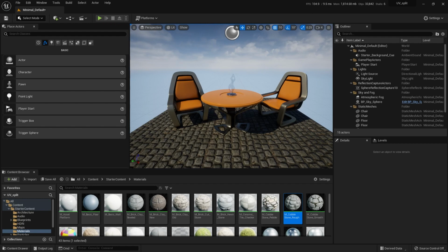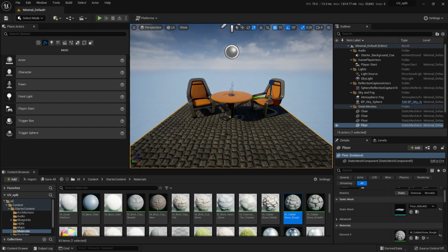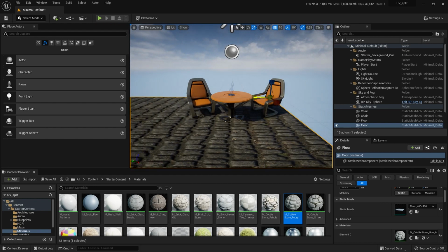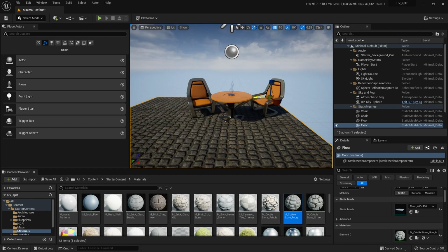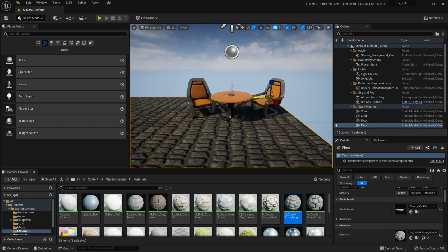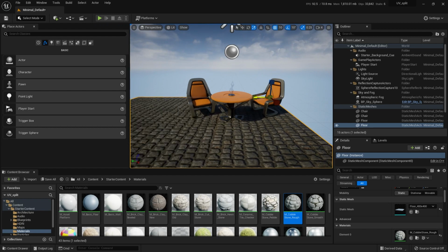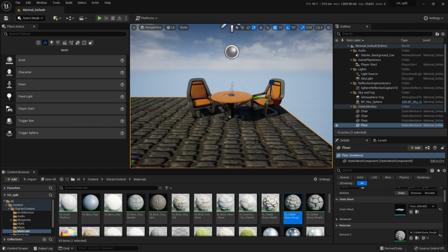Maybe you want to adjust the tiling, or maybe you're applying this to a piece of geometry that, if we select this guy here and scale it a bunch, looks stretched and weird, right? So depending on what geometry you're using, the UV layout might make for some strange looking tiling. So let's talk about how we can modify this so that you can adjust the U and V separately. Now, let's stretch this crazy out that way. So we need to stretch it only in one direction, ideally.